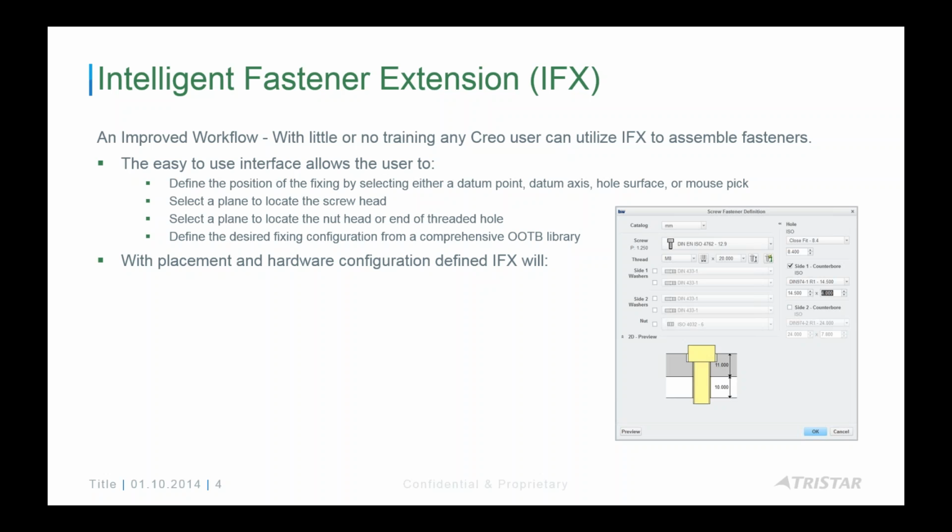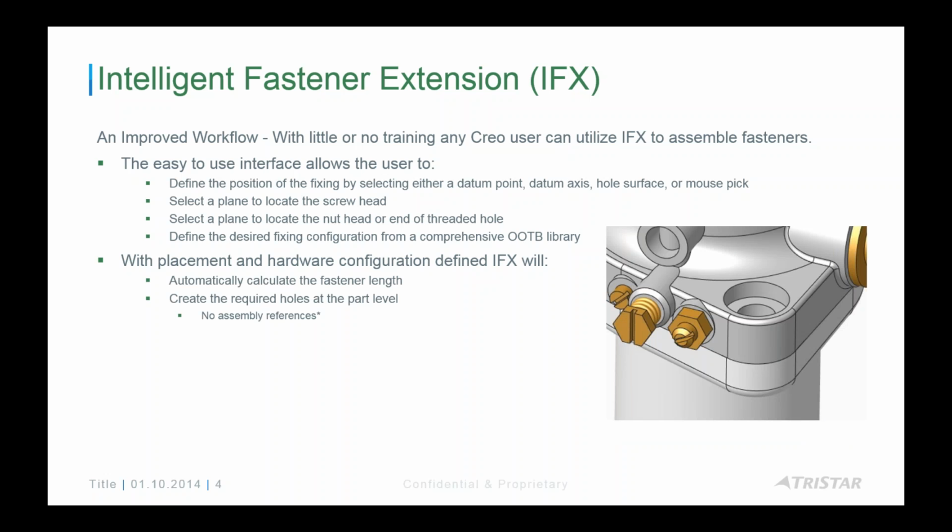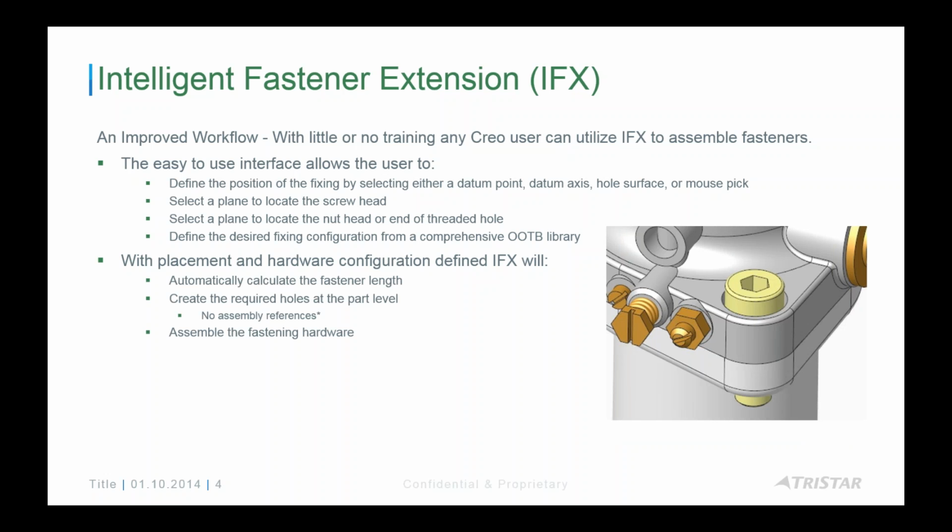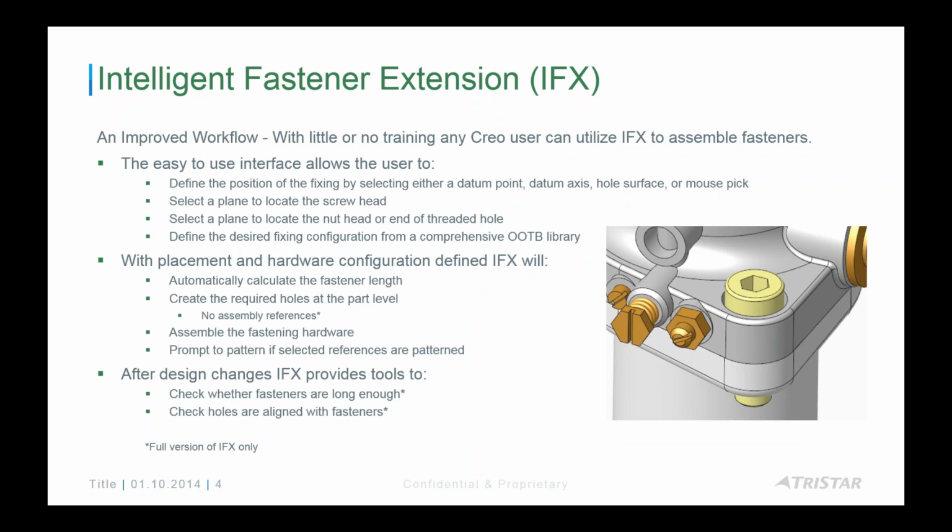Then with placement and hardware configuration defined, IFX will automatically calculate the fastener length, create the required holes at the part level, assemble the fastening hardware, prompt to pattern if selected references are patterned. After design changes, IFX also provides tools to check whether fasteners are long enough, check holes are aligned with fasteners. Some of these options are available with the full version of IFX only.